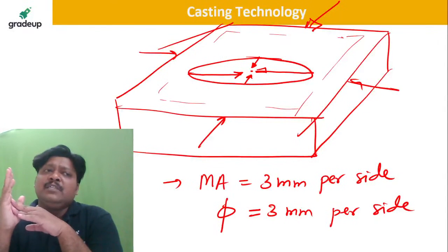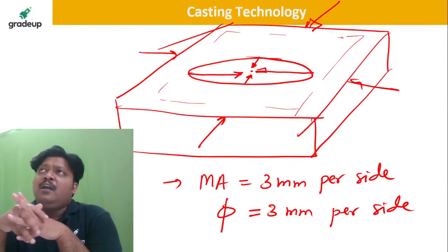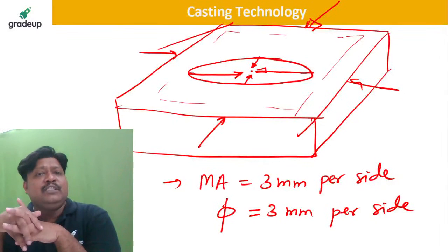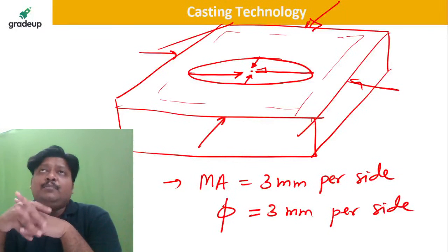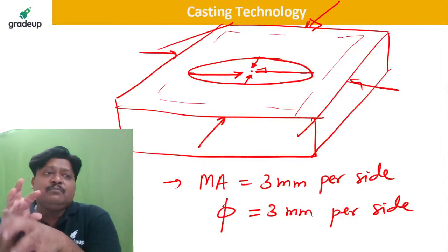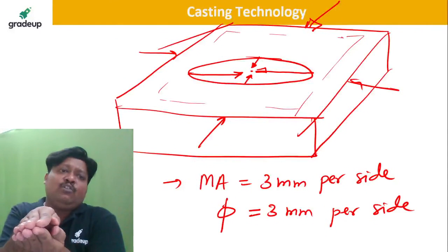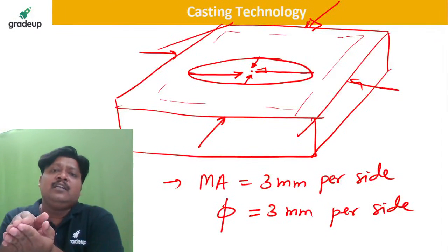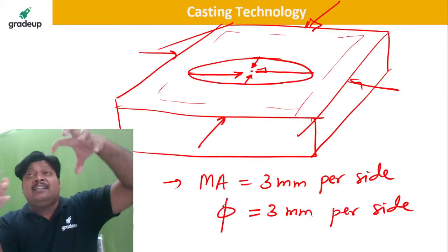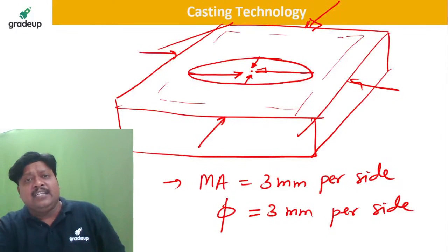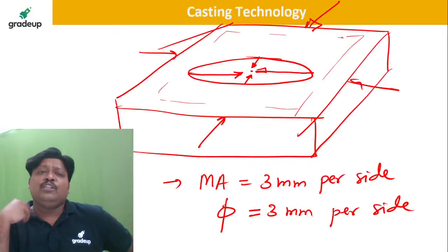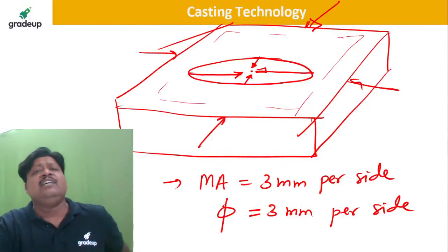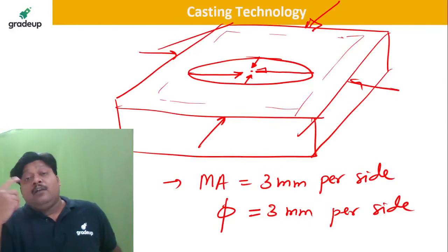So why bismuth? Dear students, whenever we are die casting bismuth, please listen very carefully. What happens when the bismuth is injected into the closed die? Whenever there are very critical impressions like letters or embossings in the die, we have to ensure that the die cavity gets filled at each and every corner. That is our intention.